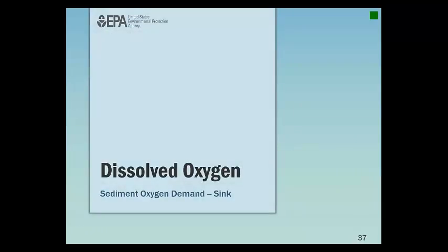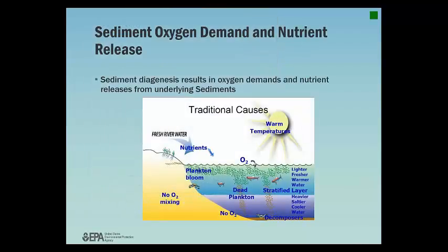The last process that we're going to discuss in the dissolved oxygen cycle is sediment oxygen demand. Sediment oxygen demand and subsequently nutrient releases is a function of sediment diagenesis or decomposition of oxygen-demanding materials in the underlying sediments. These sediments are recipients of the settling of dead biotic material and organic materials from the watersheds, and are actually a function of the external loadings to the water column.